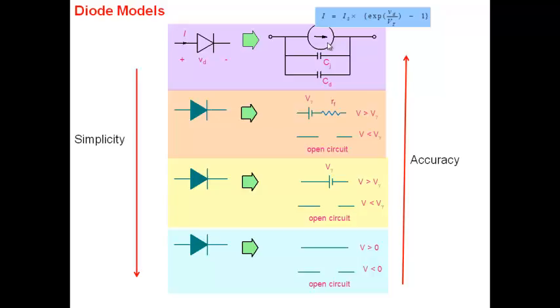by actually building it, by actually building the circuit. So you take a diode and you actually build it, and then you'll get the most accurate value. Because remember, all these models are again approximations. When you read a data sheet, for example, there's a diode called 1N4148, or there are many kinds of diodes. If you just go on the internet and read a data sheet of a particular diode, you will see the manufacturer would give you some values here. Let's take IS for an example.